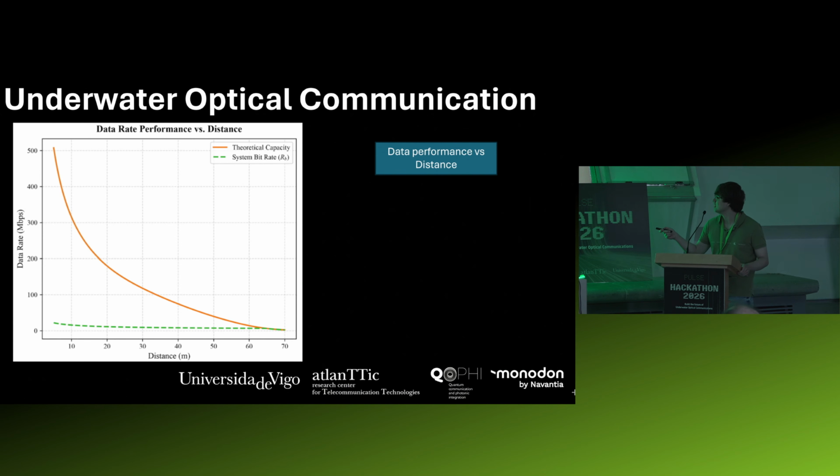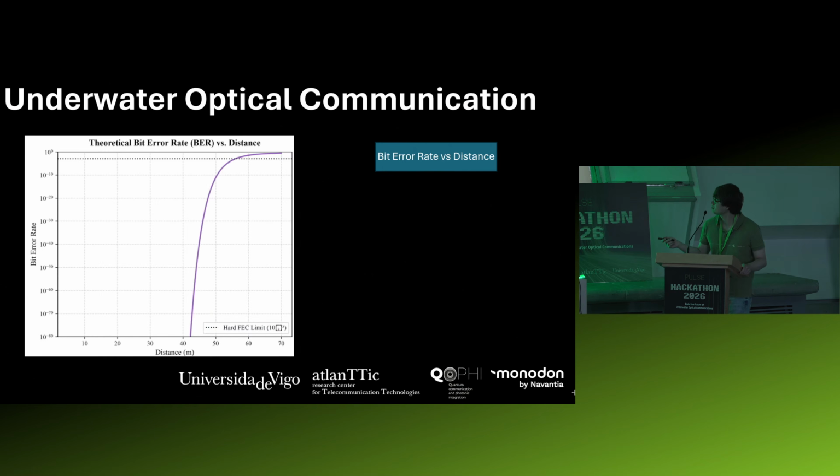And although that's funny, with our modulation, we have to keep in mind that the actual binary rate that we can transmit is the lowest we can get, because OOK is not particularly efficient with its information conveyance. So this sits at about 20 megabits, and it stays roughly the same, as stable as it can get. And it caps out when the capacity of the channel also bounds the upper maximum capacity.